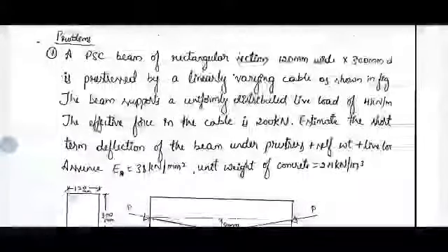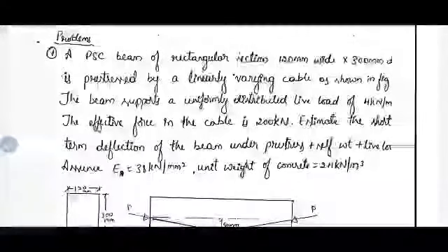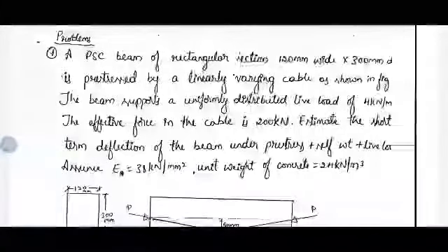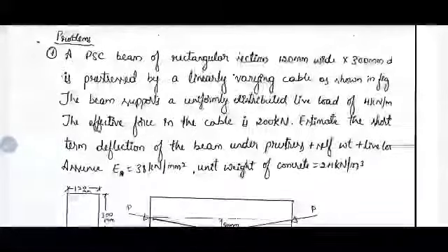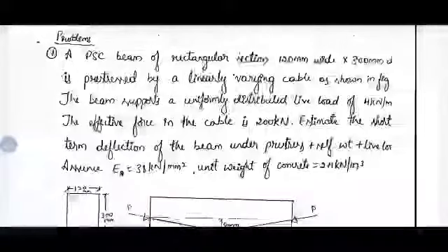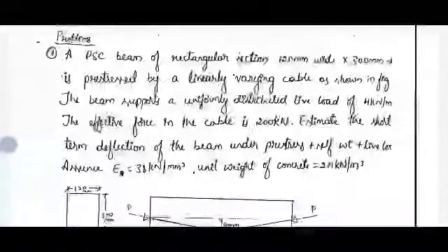Hello everyone. Today we will discuss problems on deflection of PSC members. First problem: a PSC beam of rectangular section 120 mm wide, 300 mm deep is pre-stressed by a linearly varying cable as shown in figure.